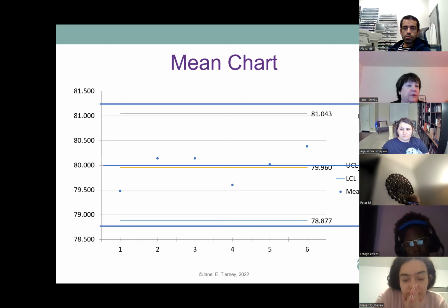Lot 3 looks very much the same. Lot 4 is not quite 80, so the average of that is going to be a little bit lower. Here's lot 5, which is right on that 80 number, which is looking good. 80.4 here, and then we've got down to 79.5 right in here. Those are representative. They're the average of the dimension on the samples that we took, so that's representative of that lot.